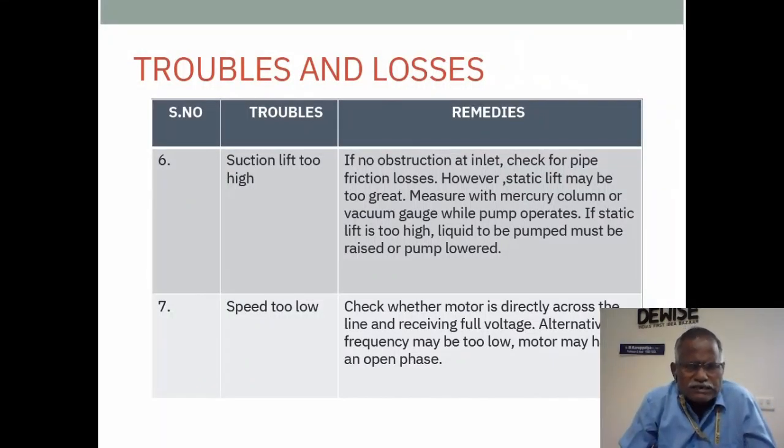Speed too low. Check whether the motor is directly across the line receiving full voltage. The alternating frequency may be too low. The motor may have an open phase. Okay.